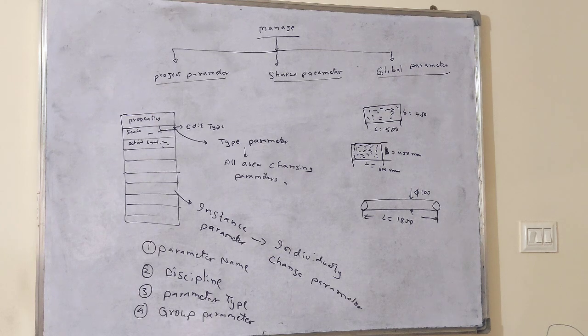Now if you select this grid, the parameter is updated, and it is updated only for this component. But if I select another grid, there is no yes here, because I kept that for this grid only. Am I right? This export to IFC, yes, I kept this information for this grid, but for the other grid I have not kept it, so it is not changed.